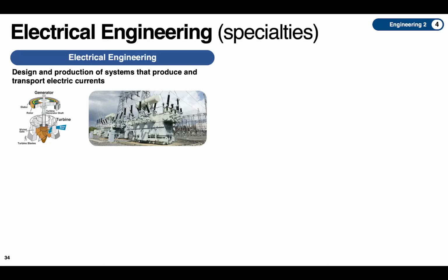And they need to exactly match the demand in real time. The reason is that electrical power at this scale cannot yet be stored. We don't have batteries that store thousands of megawatts. So we have to adapt exactly to demand. So the whole electrical power plant to consumer network has to be very finely tuned. It cannot be overpowered because it's going to damage the transformers and wires, etc. And it cannot be underpowered because you will have power outages. So managing it is like a very finely tuned dance.